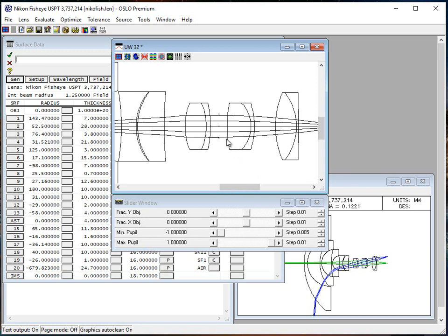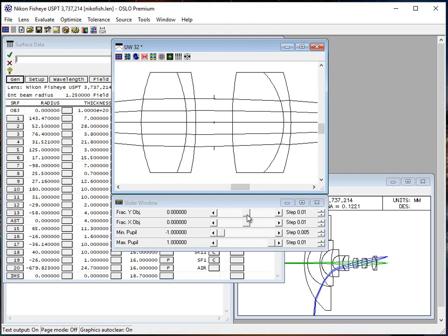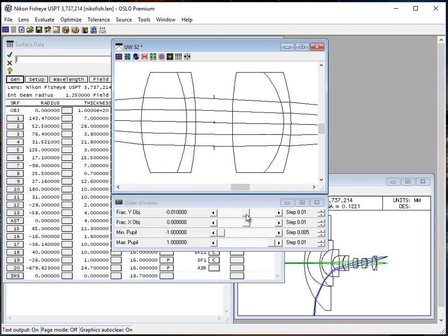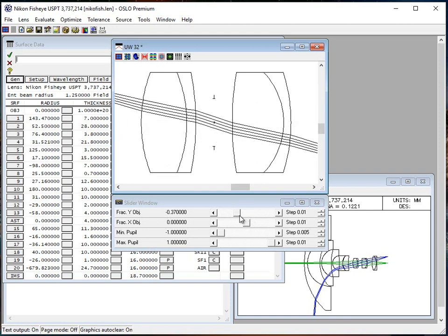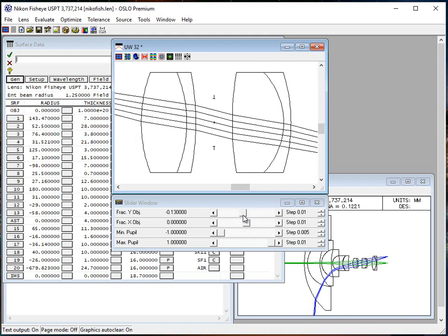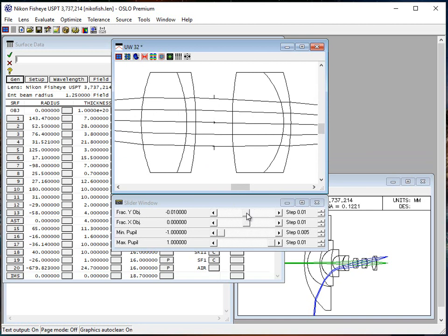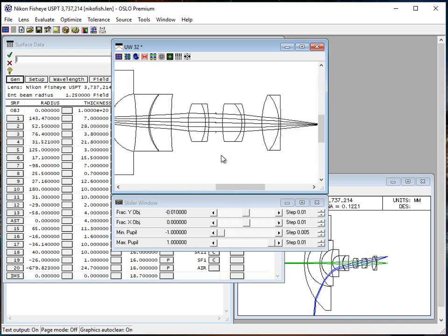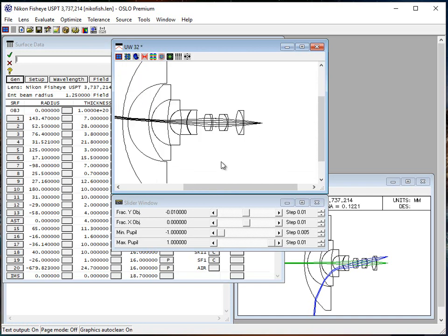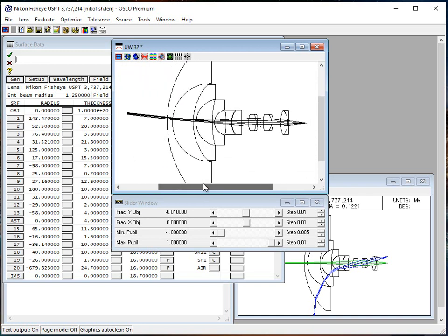But this one does not get the rays out to the edge quite correctly done, and we can see that here. What I've been changing down here, by the way, is the field of view. So as I change the field of view, whoa, look at that. The bundles get a lot smaller. What this means is the pupil aberration here is such that the predicted ray bundle that's needed off axis needs to be a lot bigger than what the program thinks it's going to be in this particular ray aiming mode, and so the bundle ends up being too small.